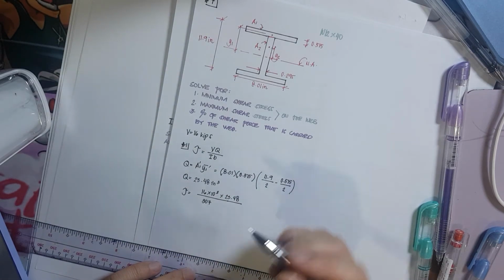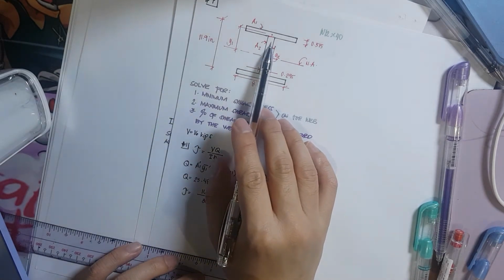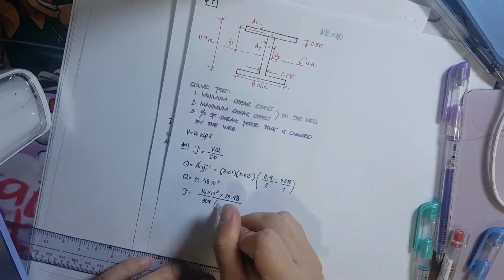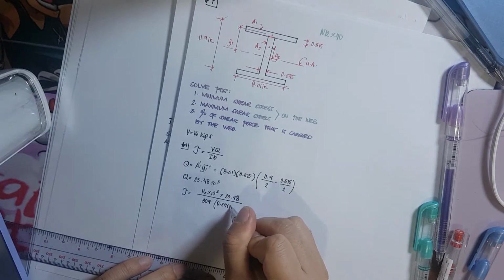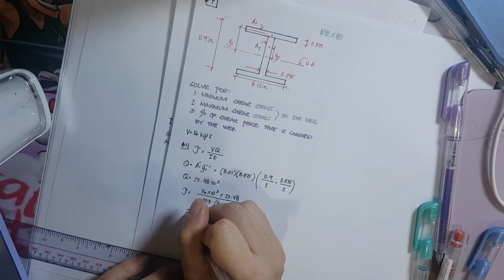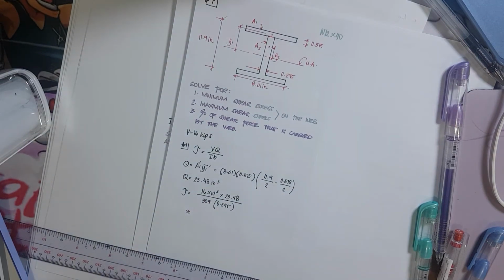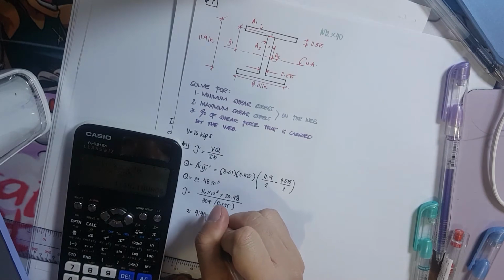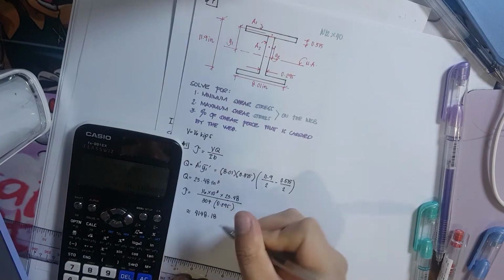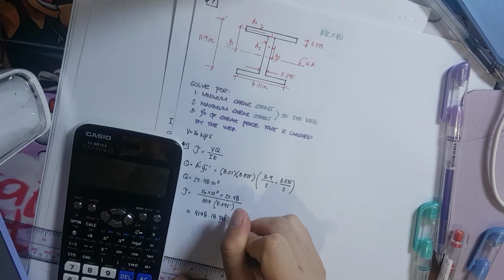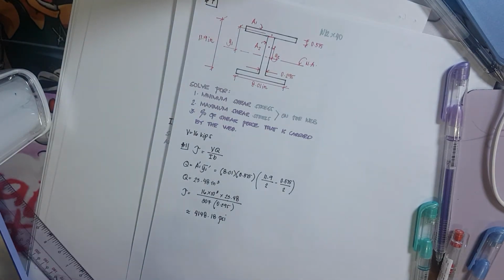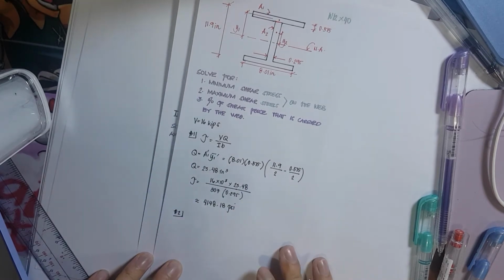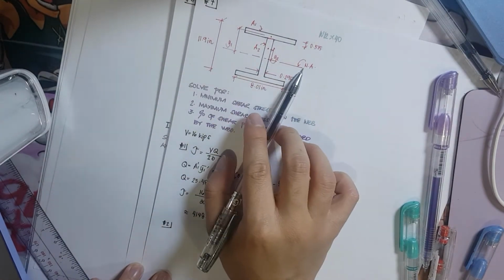Then for the B that we're going to consider, or the thickness, would be the thickness of the web, and that is 0.295. Therefore, shear is equivalent to 4,148.18 psi. That is the minimum. Now, for the maximum, we have here number 2. For the maximum, it will occur at the neutral axis.